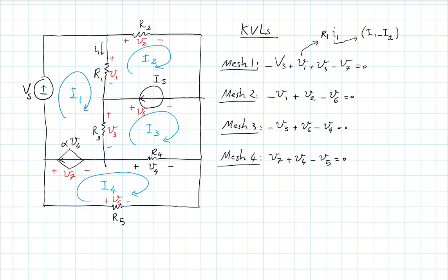Thinking about that example with cars in a street or positive charge, I1 is in the same direction as I have defined little I1, and I2 is in the opposite direction. Okay? So that's that. And so now I have replaced the little voltage V1 as R1 times big I1 minus big I2. And then I'll do the same for all the other voltages.